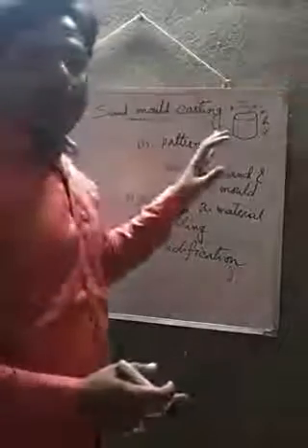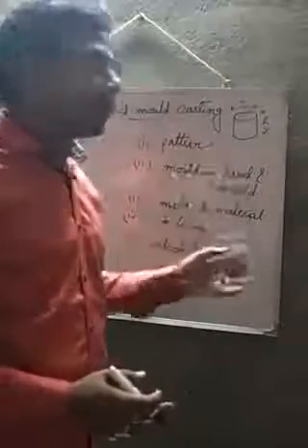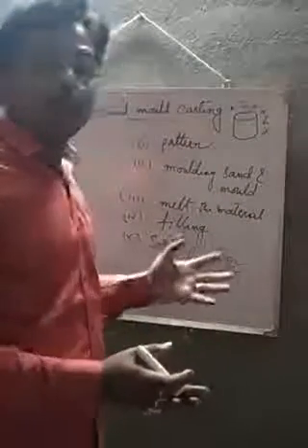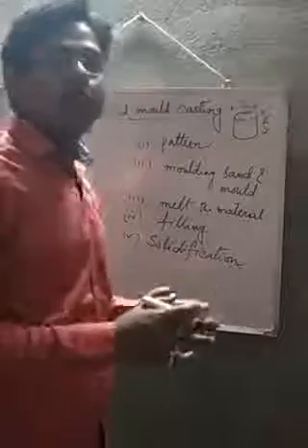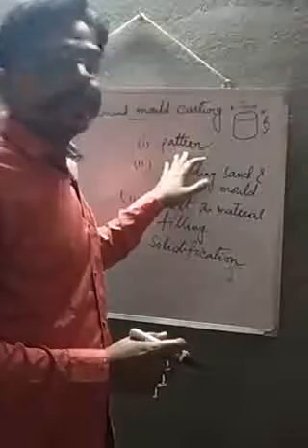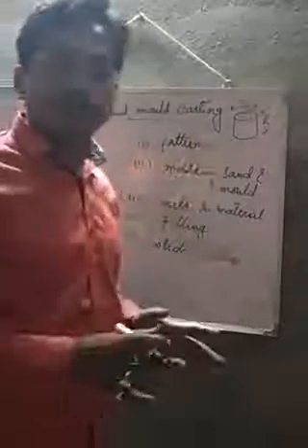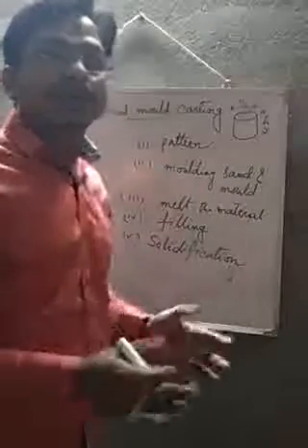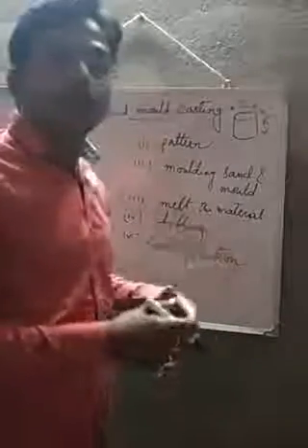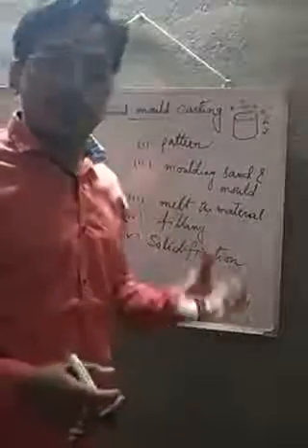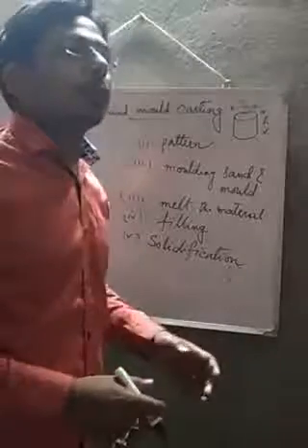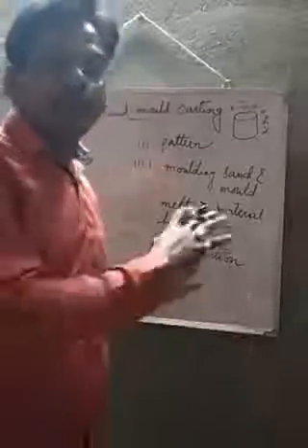We use metals like cast iron, brass or aluminium for patterns which we use repetitively, and also where we use machine ramming for making the mold. At the time of preparation of the mold, either you can ram the sand manually, or sometimes we use a machine, whose vibrating action we use for making the mold. In those cases we use a metallic pattern. According to our requirement we choose the right material for making the pattern.